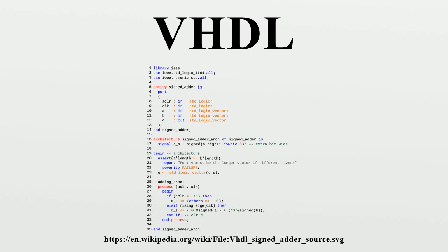One can design hardware in VHDL to produce the RTL schematic of the desired circuit. After that, the generated schematic can be verified using simulation software, which shows the waveforms of inputs and outputs of the circuit after generating the appropriate test bench. To generate an appropriate test bench for a particular circuit or VHDL code, the inputs have to be defined correctly. For example, for clock input, a loop process or an iterative statement is required.